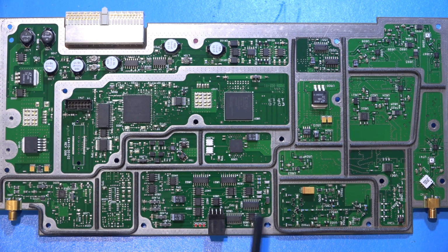So where do we test? Oh, by the way, here is another section over here. This section seems to basically detect whether there's a lock or an unlock condition. That's why you have the 3 LEDs here. There's also a couple of test points, one here and one here. I suspect that because these test points are so close to these LEDs, we should be able to use them to figure out if the system is locked. I think these are used during testing or debugging.